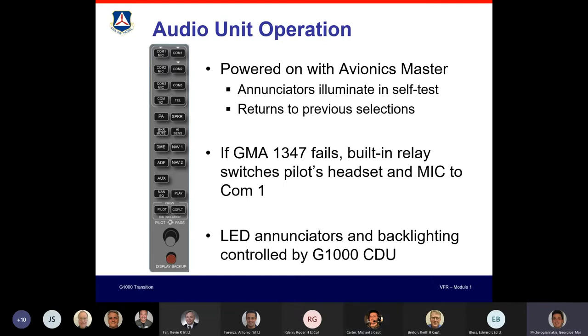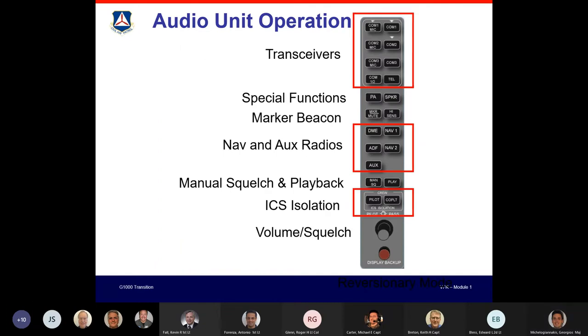So if you're the pilot and the crew is speaking and it's important and ATC wants to talk to you, so you don't want to hear everything, you can isolate yourself. The key is to remove the isolation when you're done. Otherwise, the crew is talking to you and you're not responding. That has happened to me more times than I can remember right now. And when you're done, if you don't want to be isolated anymore, just press that button again. I think that's stuff we talked about.